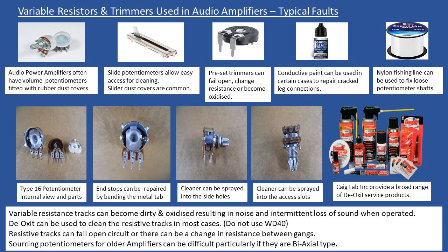All good. But you get to a volume control and maybe it's a little bit difficult to rotate, and you go in there and you clean it, and what you find is that some of the original lubricating grease, which had dried hard, starts to dissolve, and then you refit it, and you put the volume knob on and it feels loose, not terribly loose, but it doesn't feel that great when the customer's rotating it. It feels a little bit sloppy, and you think, I've got to go out now and source a replacement potentiometer, and maybe it's one of these which is like a unicorn trying to find one.